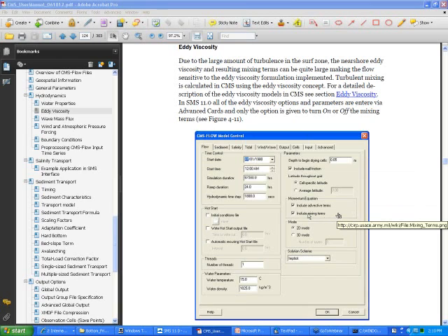So really, for practical applications, it doesn't make sense to turn off advection and mixing. One way you can turn off mixing is by modifying the coefficients to the model. You can set all the coefficients, the base value, to 0, and then you have 0 mixing. But we don't recommend that. These are going to be removed in SMS 11.1.